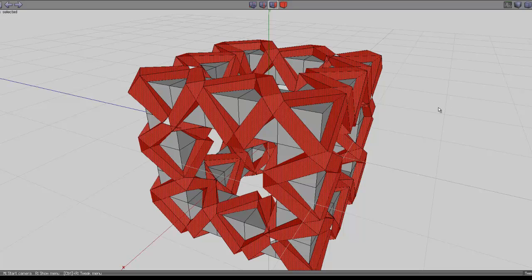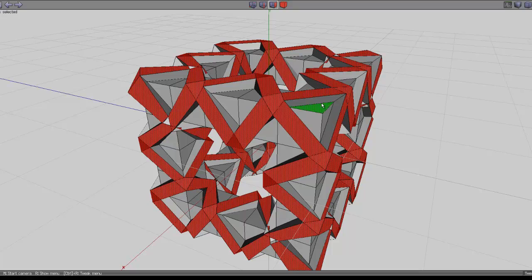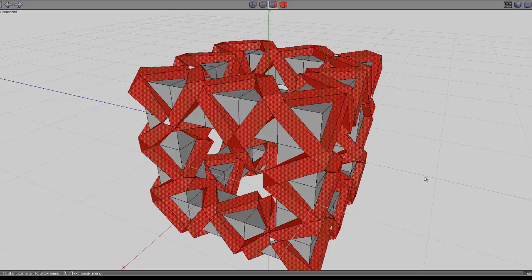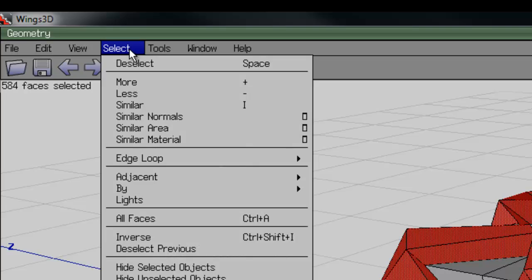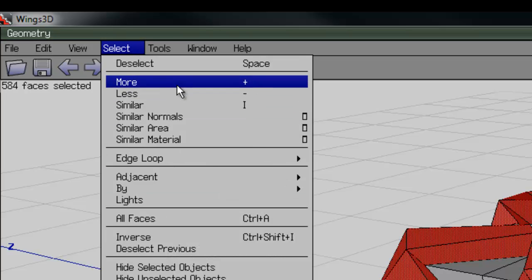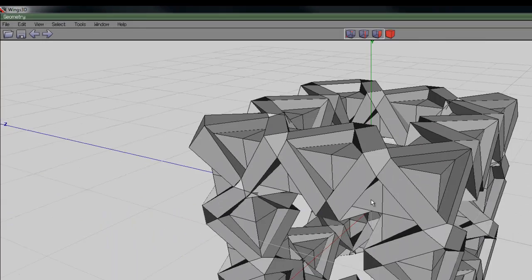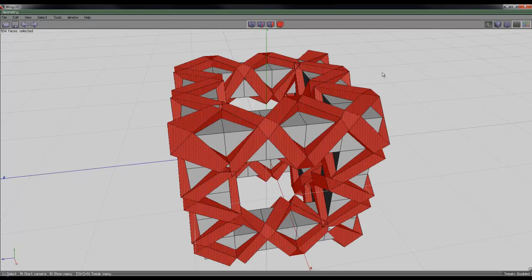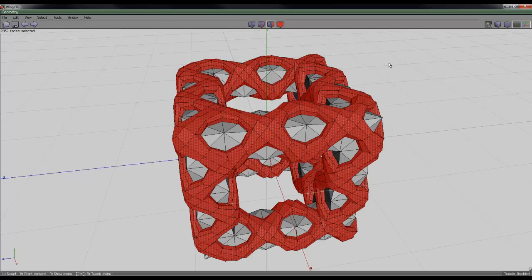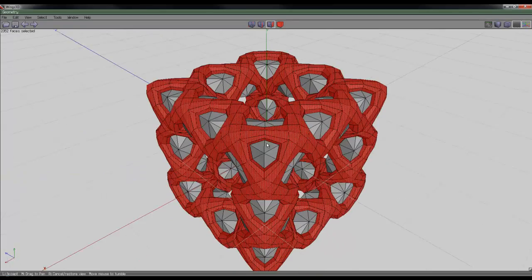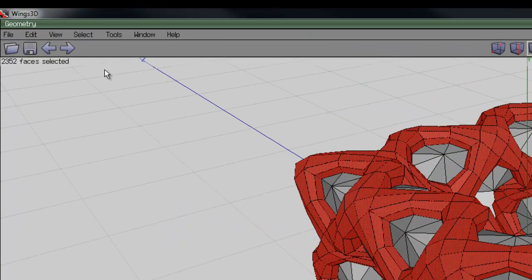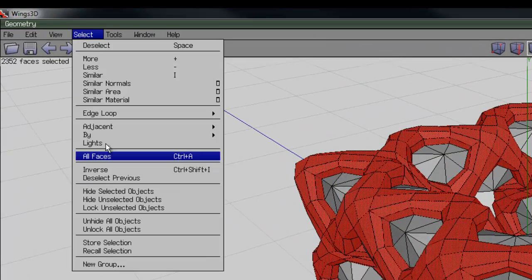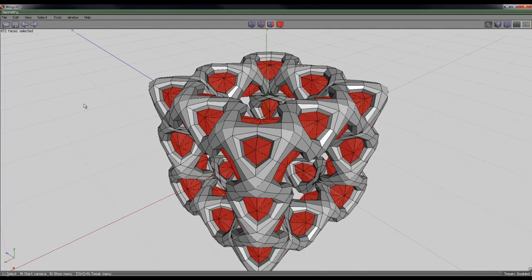Right, and now press plus, and that selects the sides that are adjacent, so you can go minus and that deselects the sides that are adjacent to the selector, or plus and that selects them in. There's also the option to do it on this select menu up here if you wish. Right, Control Z will take me back to them being selected. Now press S to smooth those, so that's smooth the outer, and then go select and inverse, much like the two-part cube, but we're not going to split it this time.